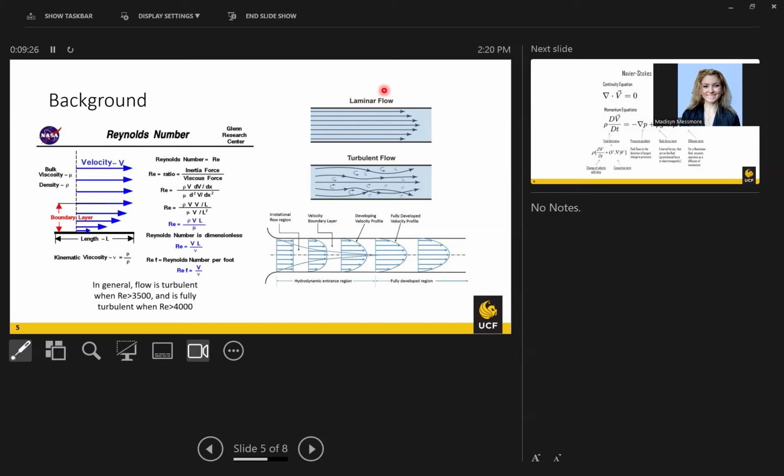There's also other cases where you can have a lower Reynolds number and there's still turbulence, but that's a more heavy fluids topic that we don't want to talk about. But is this only for internal flow? The Reynolds number 3,500, 4,000 is a generalization. In every fluids class, Lucy's fluids class, he always just said in general, that's your rule of thumb. I can't tell you for external flow because I'm not aero, so I never looked at external flow. I've only ever looked at internal.